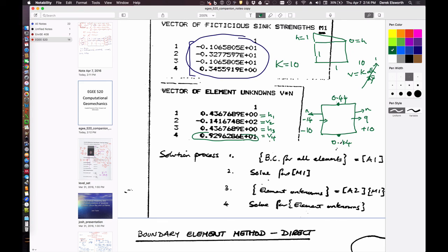And so it's a lousy, well, it's not a lousy solution. And of course, if you look at how this should change as you go from upstream to downstream, this value here is going to be equal to exactly half of the head. So this should be 0.5. It's not. And so the reason it isn't is because it's really a coarse mesh. You have one element on this side, you have one element on this side, and likewise.